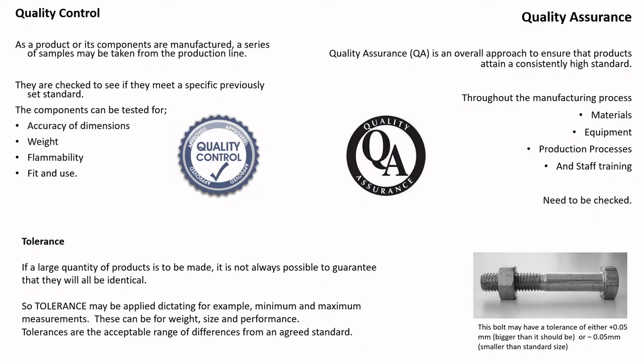Quality assurance is what you actually do to make sure it's done correctly. So how do you assure that it's done? That'll be the things you set up before. You will be making sure you've got the correct material and the correct dimensions, and there are no flaws in the material. If you're working with natural timbers, there are no knots in it, it's not bowed, it's not warped. Those sorts of things. Checking your equipment, checking it's working correctly, checking you've got the right molds, checking you've got the right size drill bit.